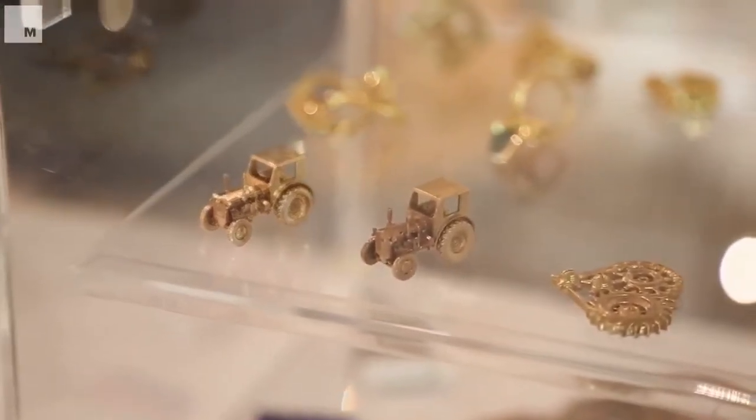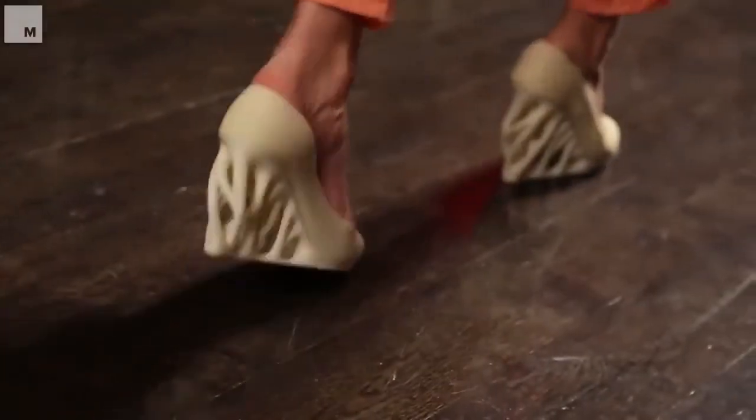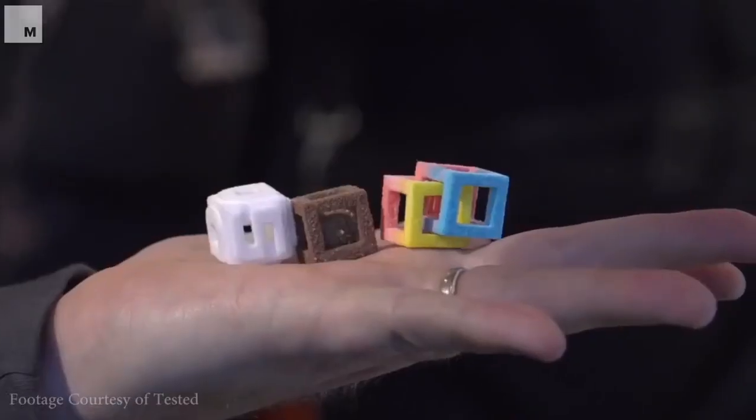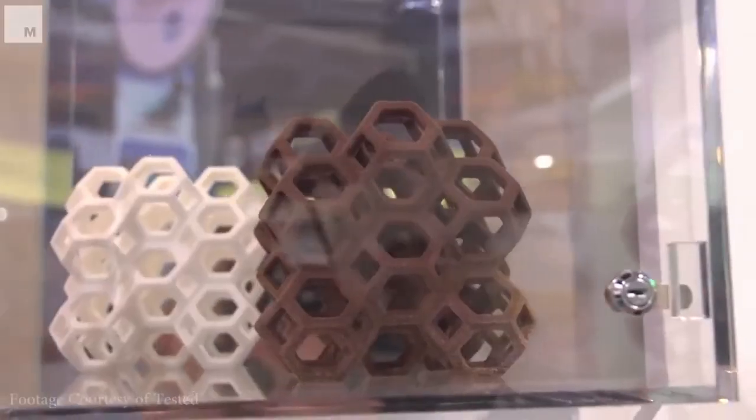There are many different techniques to 3D printing, yet the easiest way to explain the process is printing material, which is usually a plastic filament, is drawn into the extruder, which is the core of the printer. The extruder has two main parts, a hot end and a cold end. The cold end is where the motor draws the filament in and pushes it through. The hot end is where the filament is heated until it liquefies and is extruded out through the nozzle.